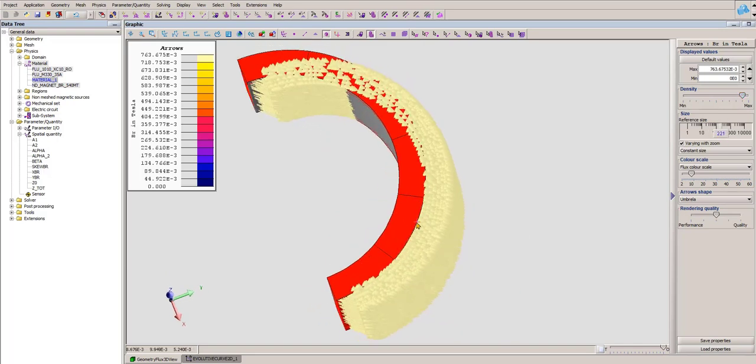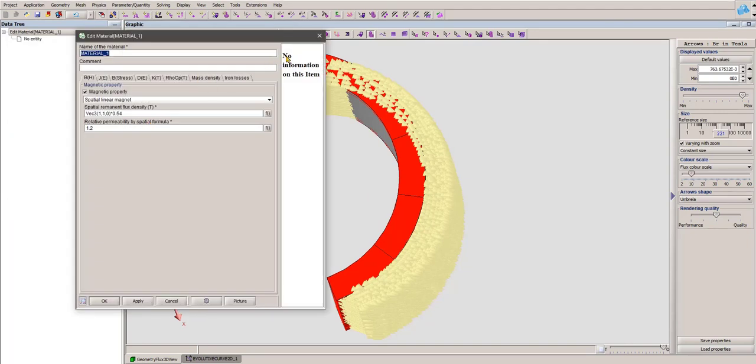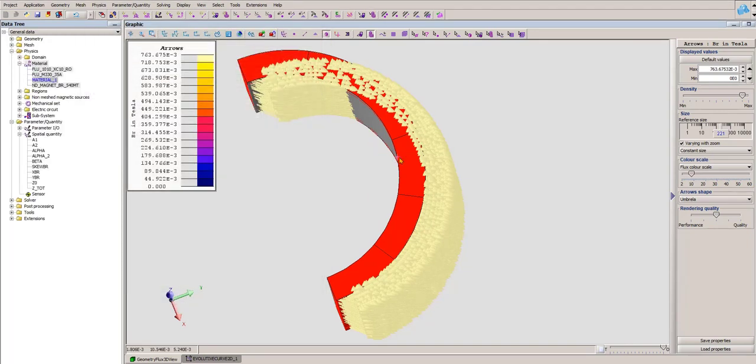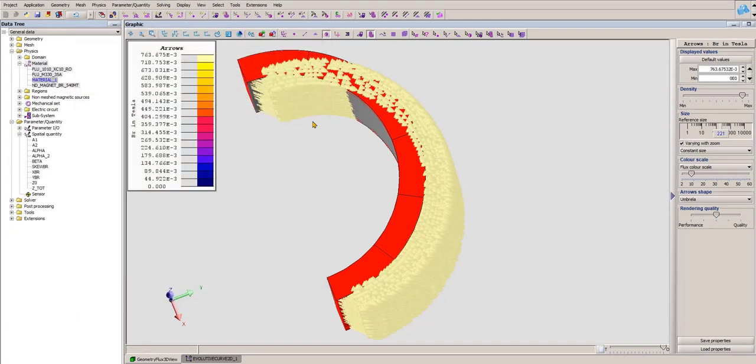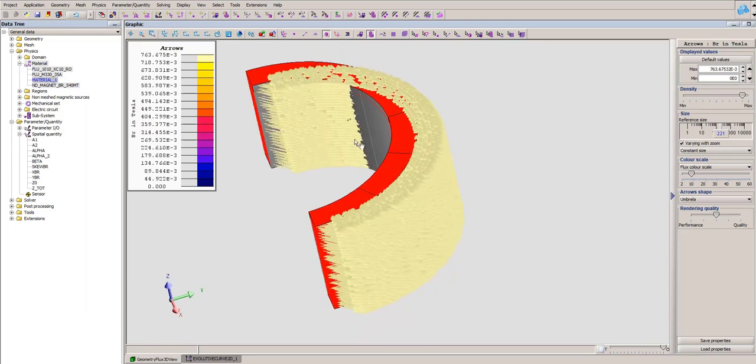If I want to make positive and negative, then I have to create parameters as a function of the valid function. I can use the valid function to say that from 0 degrees to 90 degrees I will use positive, so I will keep it as it is here, plus another valid from 90 degrees to 180 degrees with minus orientation, to make the opposite orientation. So the spatial magnetization is very easy. Let's come back to our interest, which is to create radial positive and radial negative orientation and skewed at the same time.